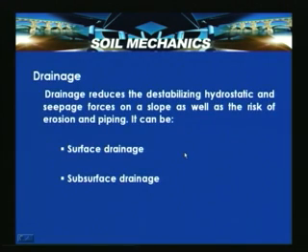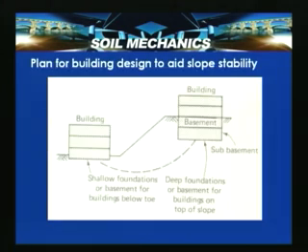So, drainage reduces the destabilizing hydrostatic and seepage forces on a slope, as well as the risk of erosion and piping. It can be surface drainage and subsurface drainage. So, the drainage phenomenon reduces the destabilizing hydrostatic and seepage forces on a slope, as well as the risk of erosion and piping.